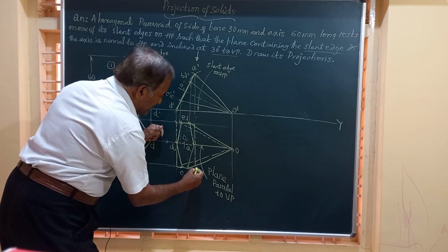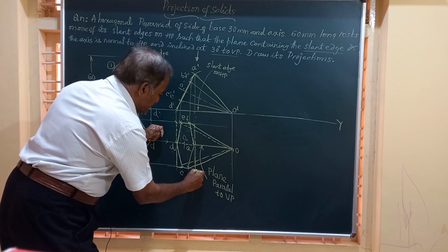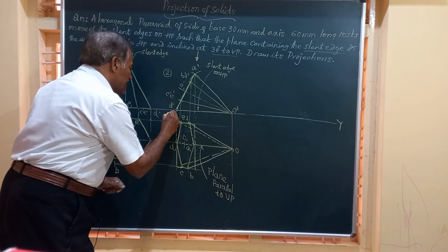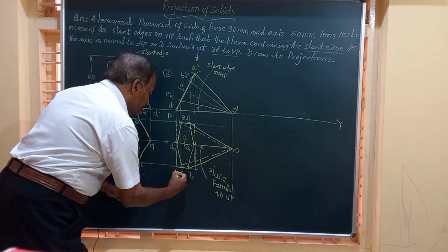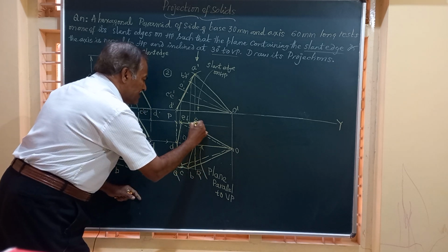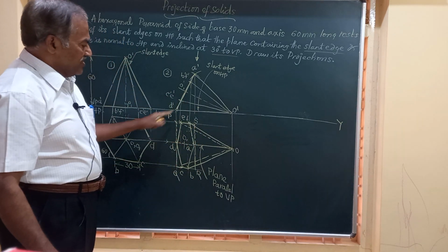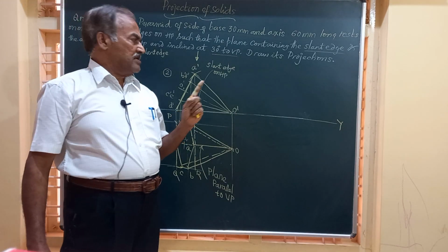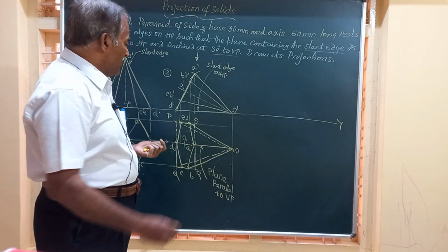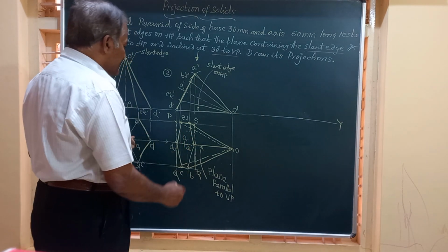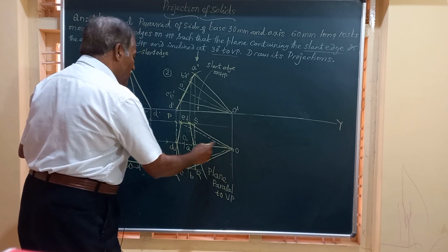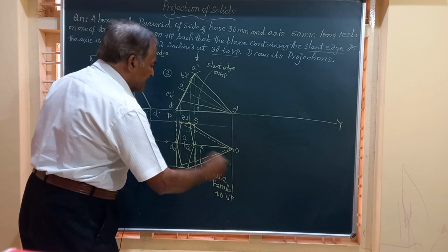So in that box will lie these 6 corners. So I will call that box P, Q, R and S. PQRS is the box in which the base of the hexagon is enclosed. So I have to redraw this such that this line OD or O1D is at an angle.